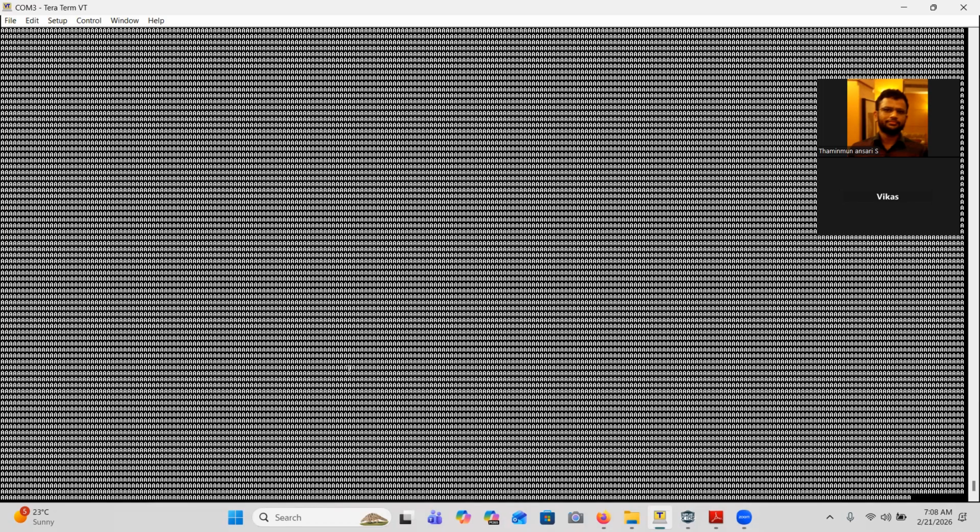My laptop has a serial port using the Prolific cable, and by default the motherboard has a serial port. When we attach both of them, the microcontroller transmits A on the TX line, that means the serial TX line, packet by packet. As we discussed before, a serial communication packet carries 1 byte. The A is coming from there.